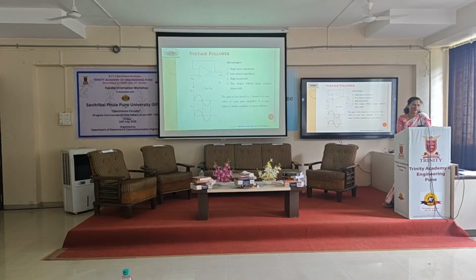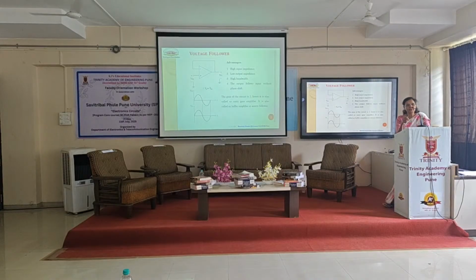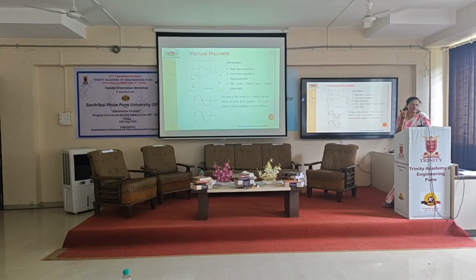And there is again improvement in the overall bandwidth. These are the benefits as compared to the non-inverting. Non-inverting amplifier has higher input impedance as compared to the inverting, and voltage follower has more input impedance as compared to the non-inverting. It has the highest input impedance. These are frequently used in signal conditioning circuits.